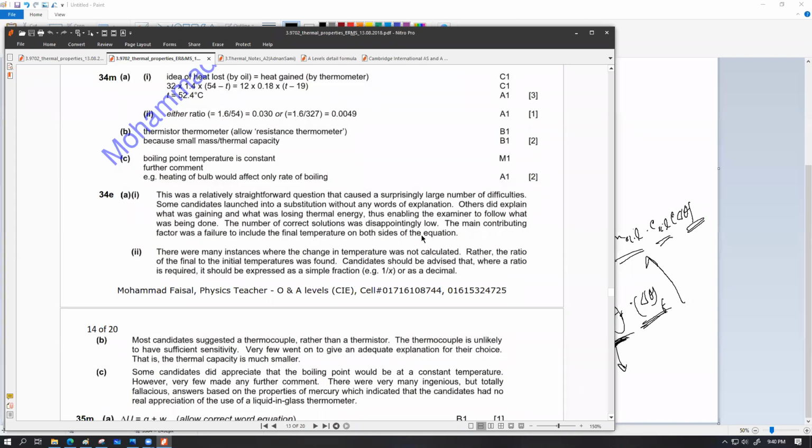No. Here's the deal. You can design the thermocouple thermometer to have a small hot junction, and the wires can also be designed to be pretty thin. In using a thermocouple thermometer, everything is taken into account. You will be measuring the voltage across the two junctions using a voltmeter inside any of the wires of the thermocouple pair. We can take into effect how much voltage drop happens because of those wires. That will already be embedded into the equation for calculating the temperature in the thermocouple thermometer for the digital output that you get. So that can be compensated for.